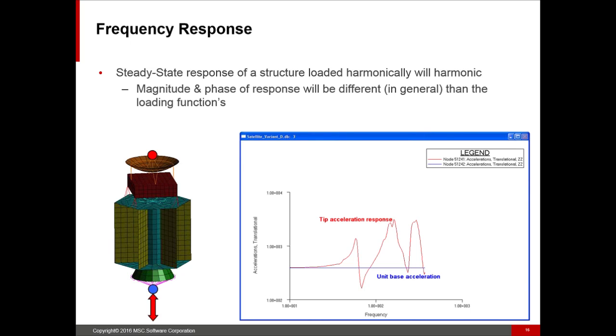One of the very common things with most structures of some sort of size is that once they get up into the higher frequency range, the response is effectively deadened out. It's because the phase in the loading, or the response from the structure, basically becomes just a one unit acceleration. So there's usually a cutoff for how high we need to go with our frequency.